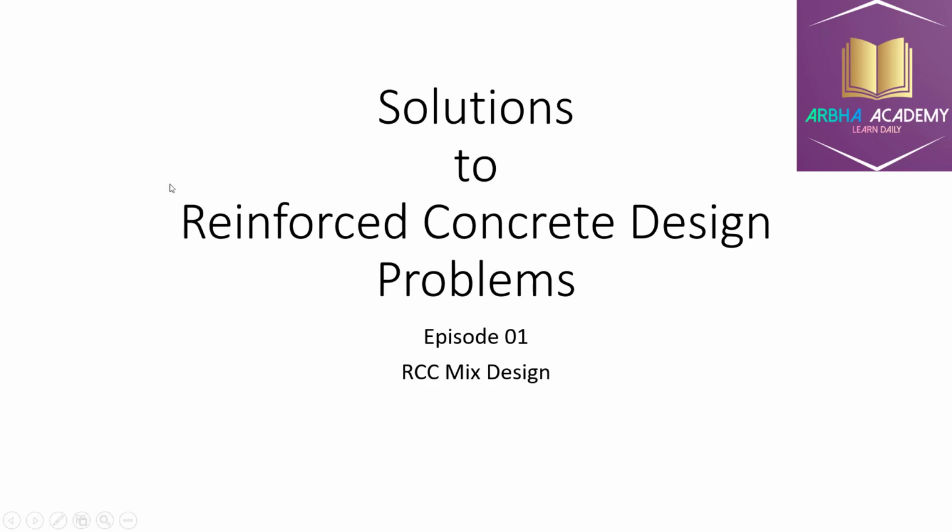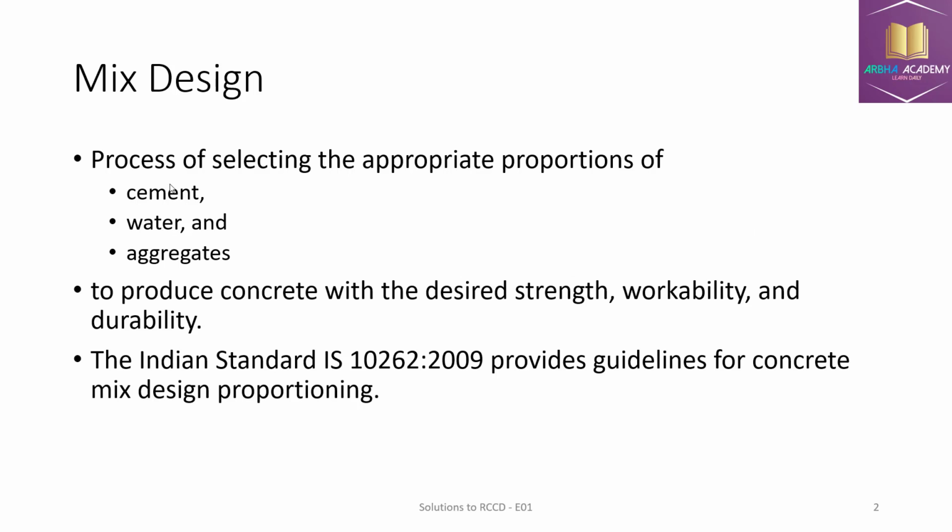Just a brief: what exactly is a mix design? Mix design is a process of selecting the appropriate proportions of materials. The basic materials used in concrete are cementitious materials, from cement and fly ash and many other cementitious materials, along with water and aggregates. In aggregates, there are fine aggregates and coarse aggregates.